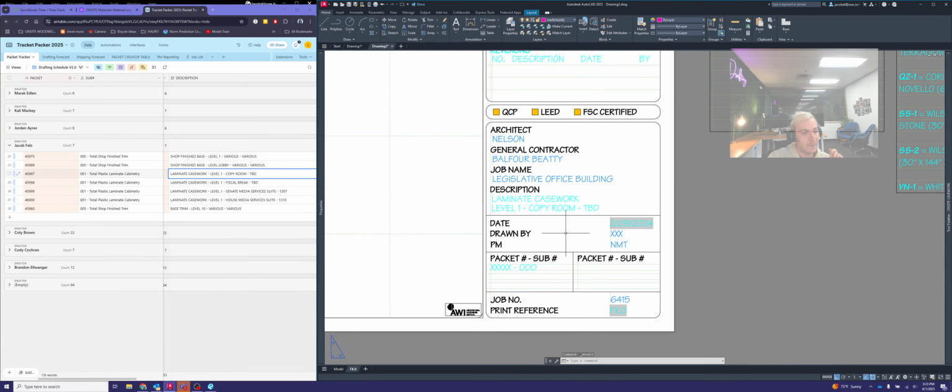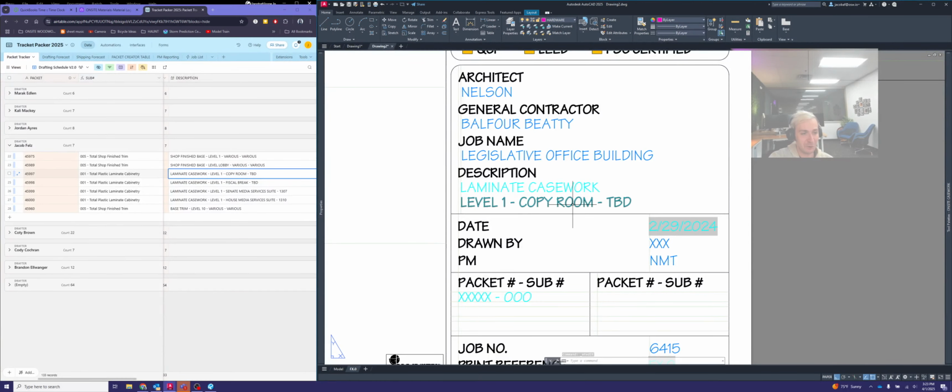And then down below in the secondary text box, you want to put in your location information for this room. Now, it always goes level number, room name, and room number. However, in this case, looking at the floor plan, this room actually doesn't have a number assigned to it. So we will write like TBD for to be determined anytime there is no information shown for that. The same would apply for like the room name. If it wasn't shown on the drawing, you would write TBD for that. And that's just a placeholder to say, hey, we're going to try to figure this out later. It's to be determined. You should always try to put the correct information in if you have it. If it's not available to you, TBD is fine. We just try not to use it as often as we can.